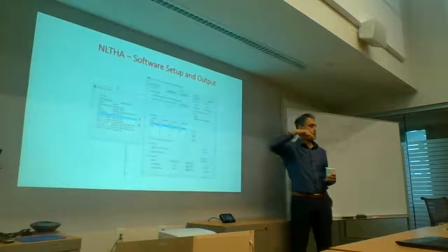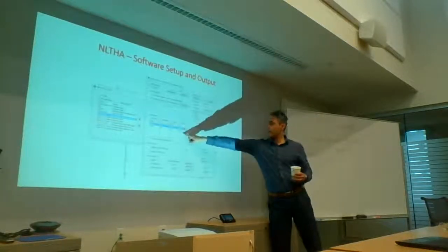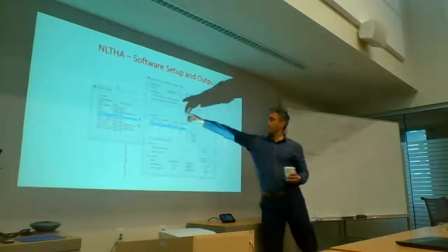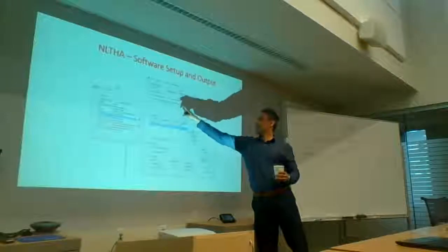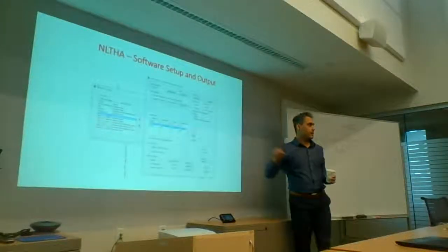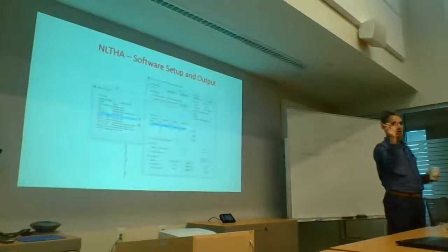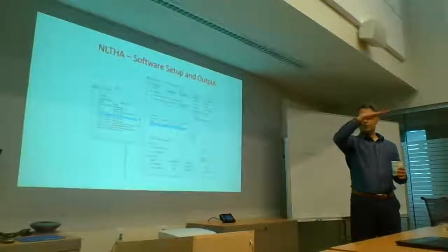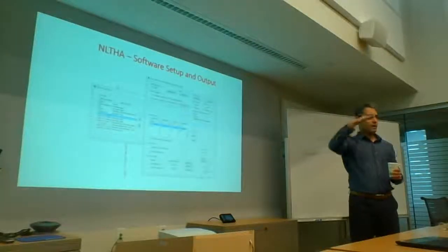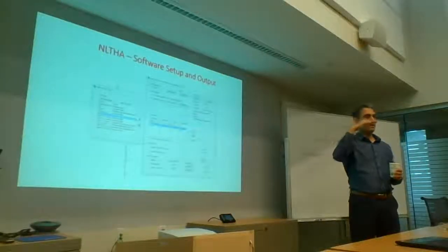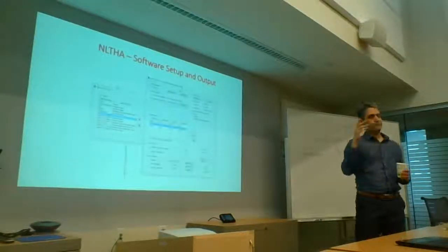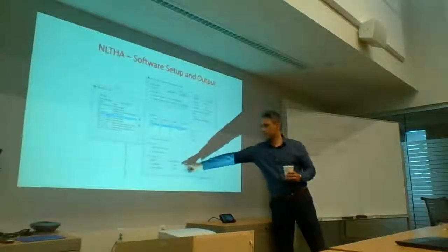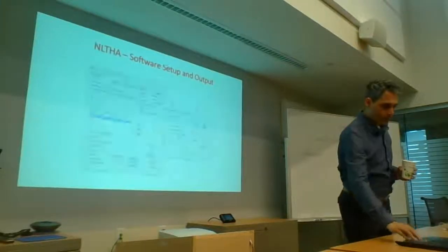I know my numbers are percentage of g, so I have factors of 9.81 in the two degrees of freedom, and I say continue from state at end of nonlinear case dead-all-plus, and the end of that nonlinear case happens at 20 seconds, right? So it just hits it quickly. It's huge damping. Now the force that's going to be in there after that, because it's all linear, is going to be unamplified, just bare dead load. And then I say, apply this from this stress state. I go with proportional damping, the Rayleigh damping that we talked about.